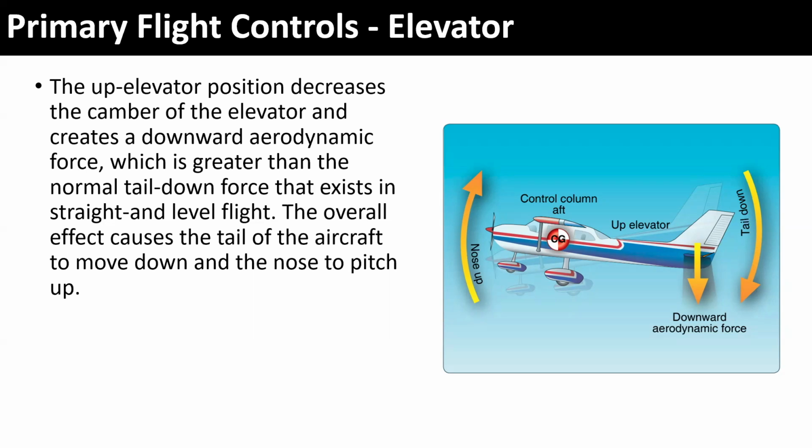Go ahead. So is that what they consider fly-by-wire? No, so fly-by-wire would be an electronic setup. This is set up with a cable from the control surface to the pilot, whereas in a fly-by-wire system, the pilot would make an input to a computer that would then send that electrically to a hydraulic system that actually moves the control surface. But good question. It's easy to think fly-by-wire, the wire going to the back. Fly-by-wire means a wire electrically.